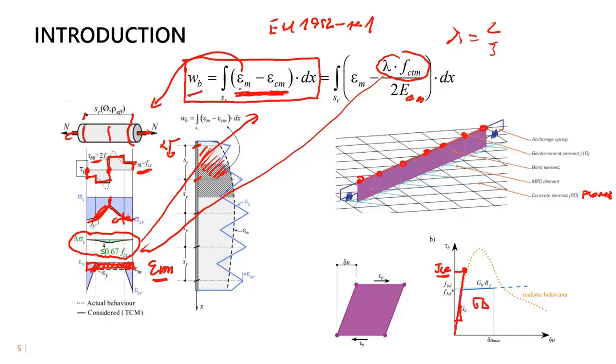Based on that, these are coupling elements, where in the bottom nodes we are utilizing multi-point constraints that are linked into the nodes of the 2D plane stress concrete wall.